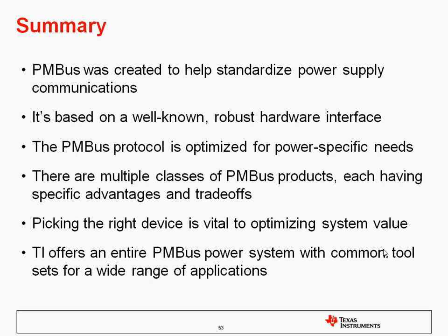So in summary, PMBus was created to really help standardize the power supply communications. We did it based on a well-known, robust SMBus hardware interface. The protocol is really optimized for power, so it has the kind of commands that you would expect it to have. There are multiple classes of PMBus products, and each one has specific advantages and trade-offs. I've given you some examples of each of them, and there will be more coming out as we release products later this year. Picking the right device is really vital to optimizing what you want to do and how your system is going to use it.